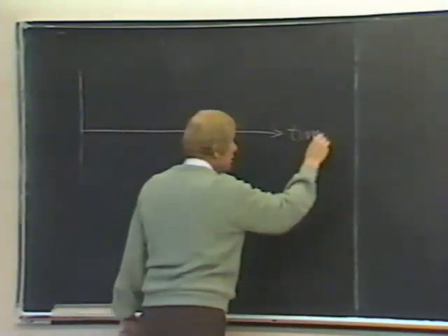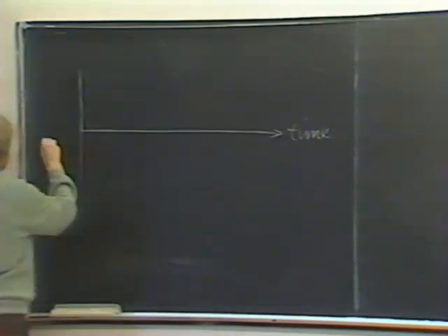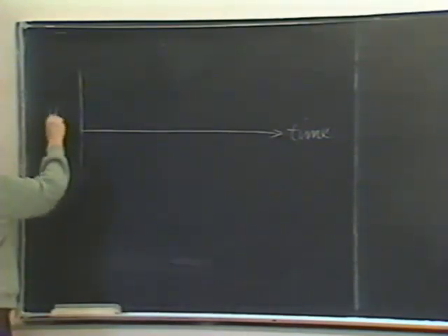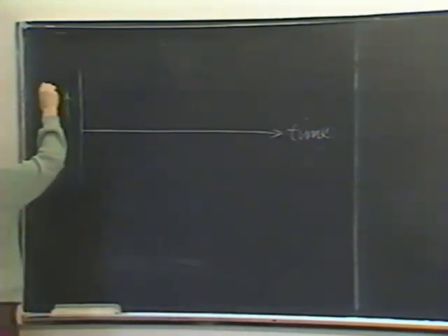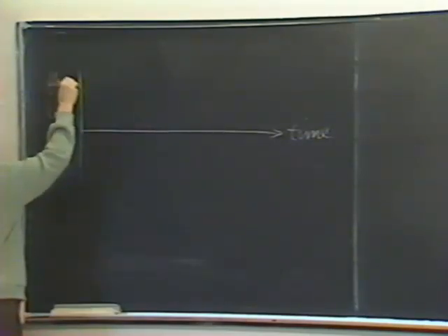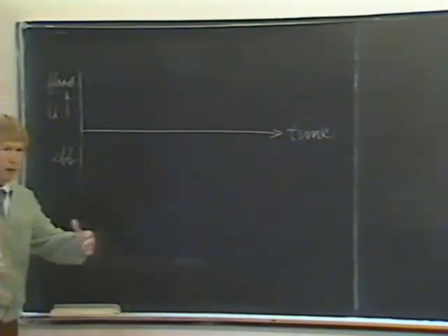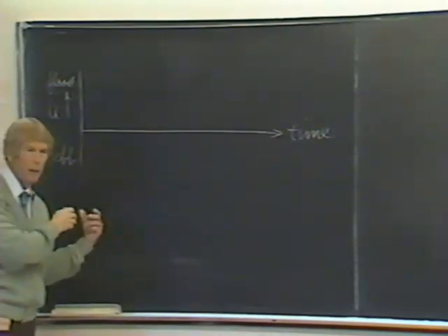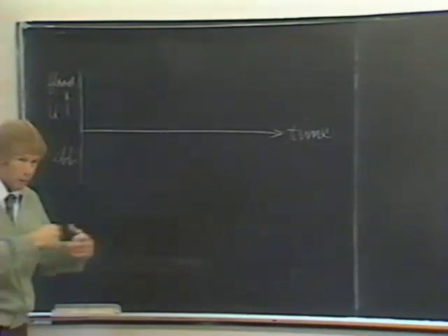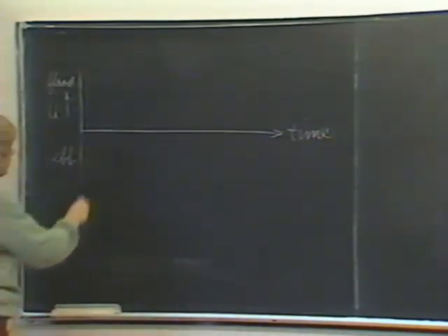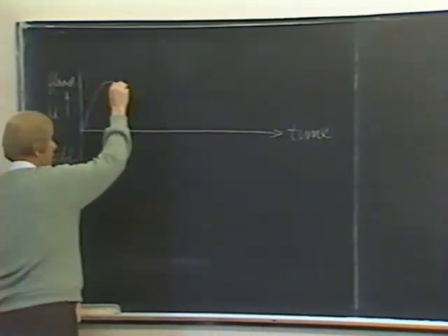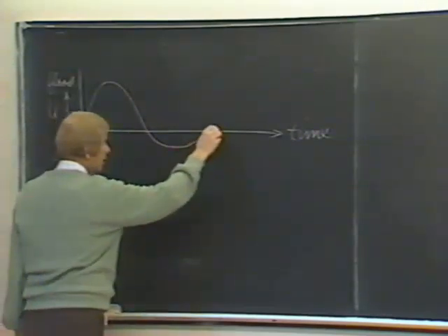Okay, so let me sum up right quick. We have the deposition depends on the aggregation of the material. It depends on the density of the material. It depends on the strength of the aggregates, that is, how susceptible they are to being broken up in the velocity gradient.